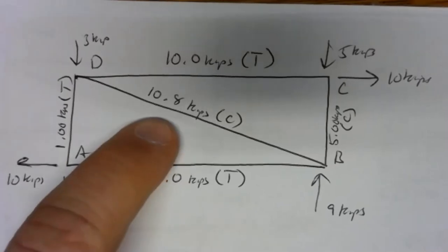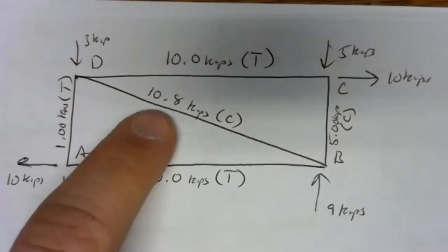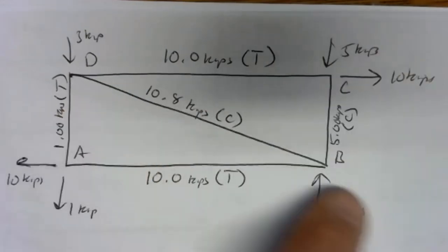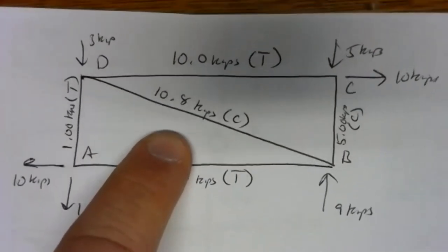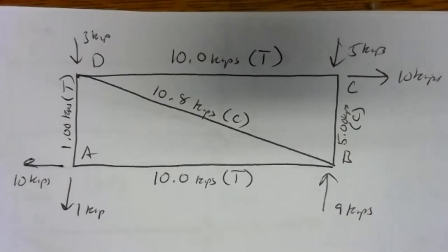And notice that it costs more force than what was applied. When you've got cross members and such, those can often have higher loads than the applied loads. So you can't just say, well, the biggest weight I'm ever going to have on this is 10,000 pounds, so as long as everything can handle 10,000 pounds, I'm good. Doesn't work. You can have higher loads depending on the angles.